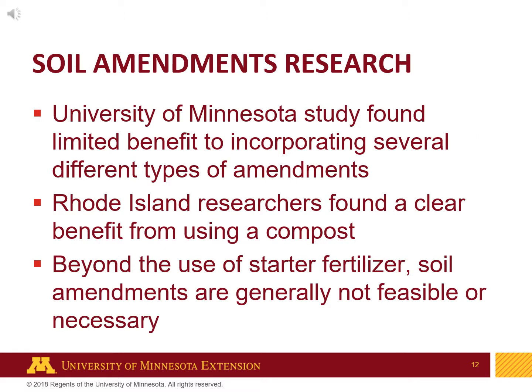We have conducted an experiment where we evaluated several different amendment types during establishment of seed and sod on roadsides, and found that there was little benefit besides additional nitrogen found within the amendments. Other researchers in Rhode Island found a clear benefit from using a compost. Our current recommendation is that beyond the use of a starter fertilizer, soil amendments are generally not feasible or necessary. If soil amendments are to be incorporated, during soil cultivation is the best time.